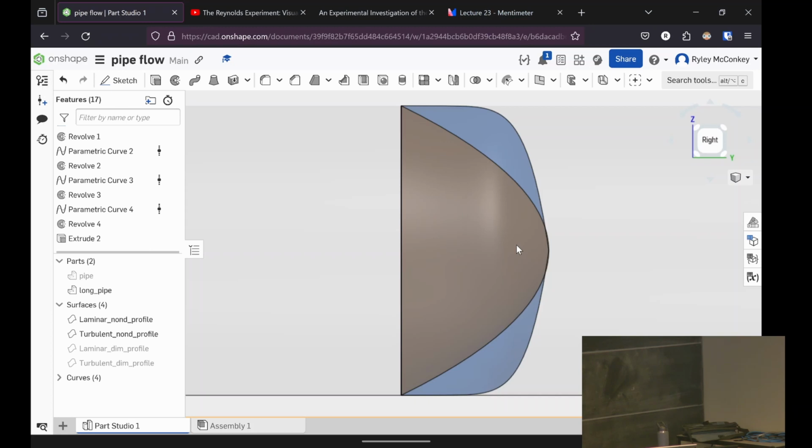I'll mention the laminar profile is derived analytically. For the turbulent profile, again, everything in turbulence is a little bit more complicated. That depends quite a bit, but in general, they look like this. They have extremely steep velocity gradients near the wall, and then they go to a more uniform profile in the middle than the laminar profile. Any other questions?